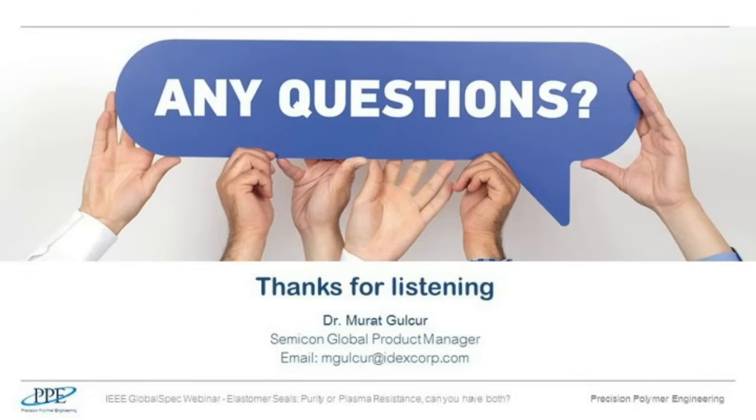First of all, our tests are done by exposing 100% of the parts to the chemistry. There is no stress, no stretch, and also it depends on the location of the seal. The failure mechanism is also very important. We don't know if the failure mechanism is leakage of the vacuum or particulation. So it's quite hard to answer this question, but we cannot predict the lifetime of a seal based on this data.